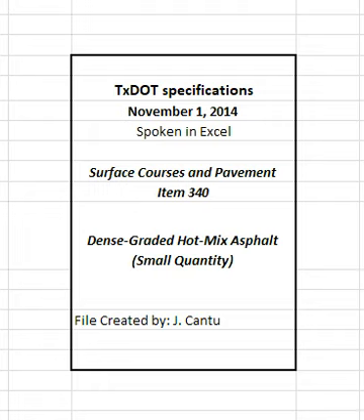1. Increase to 97% or 97.5% at the contractor's discretion or when shown on the plans or specification. 2. Adjust within a range of 35 to 100 gyrations when shown on the plans or specification or when mutually agreed between the engineer and contractor. 3. The engineer may allow the IDT strength to exceed 200 psi if the corresponding Hamburg wheel rut depth is greater than 3.0 mm and less than 12.5 mm. 4. Used to establish baseline for comparison to production results. May be waived when approved.